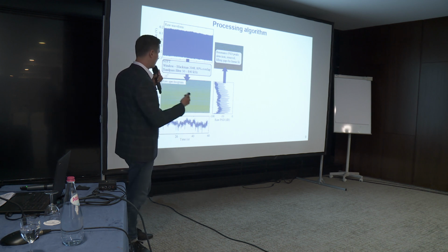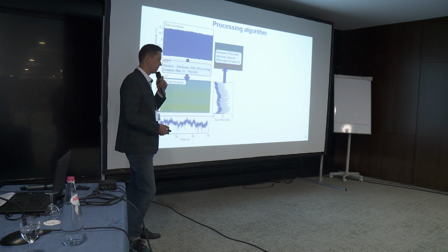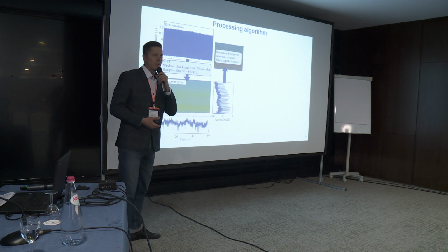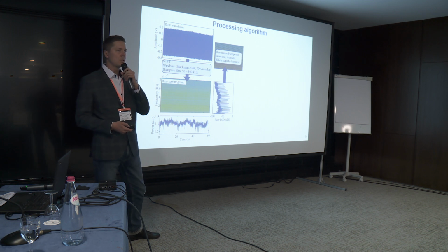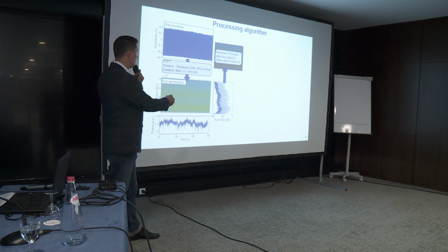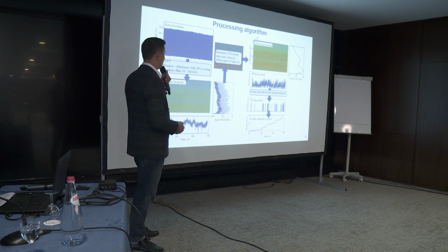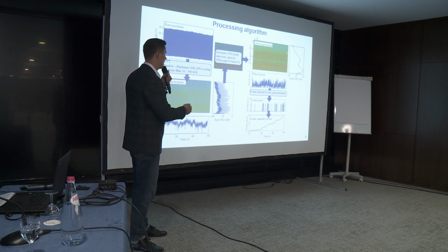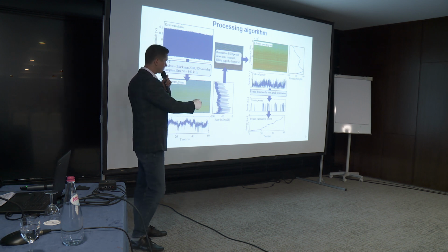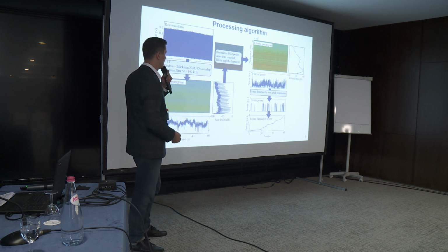The algorithm was designed in the MATLAB environment. We used peak detection and filtered all of these peaks out of the power spectrum density, and in the end we obtain a smooth power spectrum density.